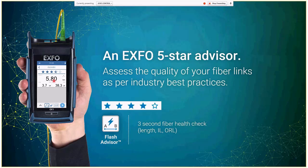So that's why EXFO brought the Flash Advisor to the market. You can have the traditional pass or fail based on your thresholds. That's also available. But the Flash Advisor will give you a comparison between the links, which is a correlation between length, loss, and RL, all in 3 seconds.